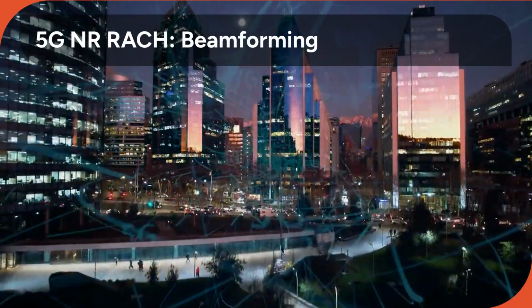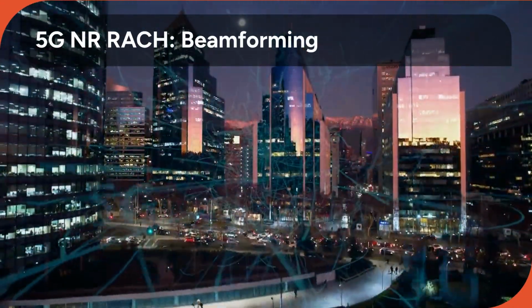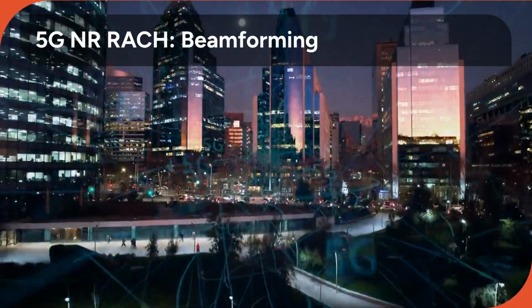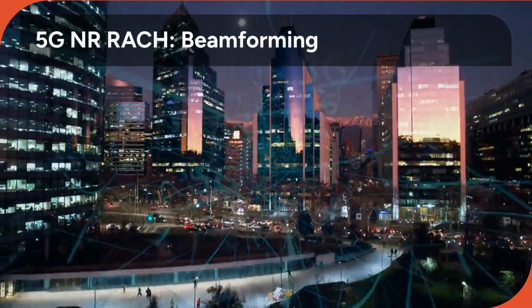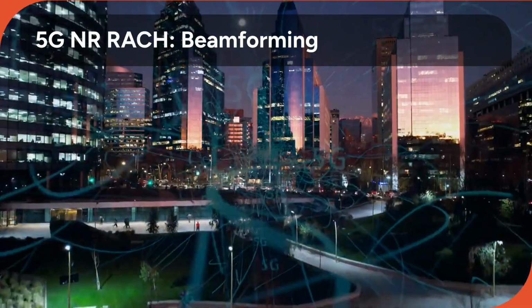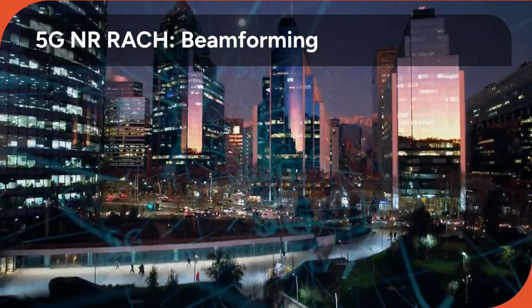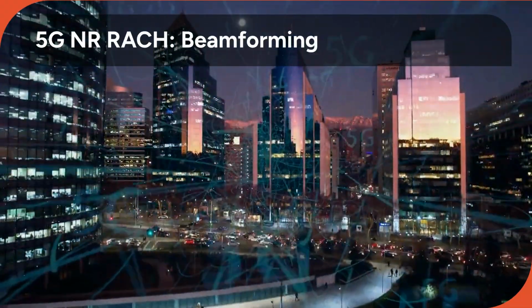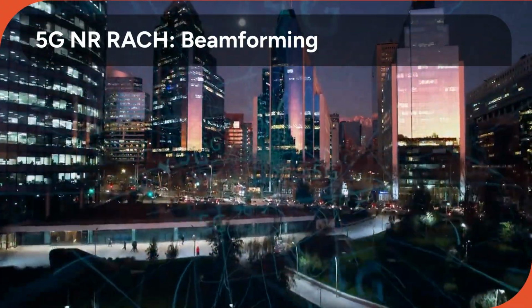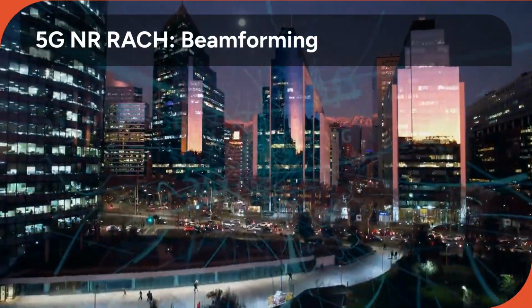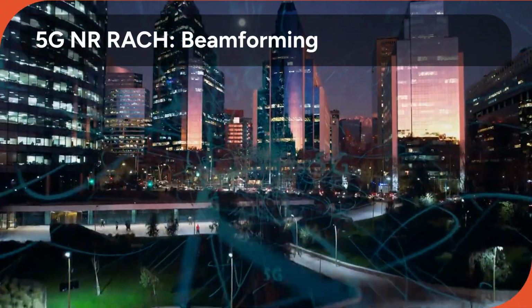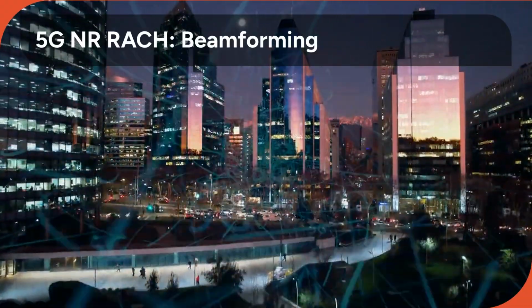Transitioning to 5G new radio, the fundamental process remains, but the context dramatically shifts due to beamforming, especially in millimeter wave spectrum. 5G RACH is inherently beam-centric. The question is no longer just, are you synchronized with the cell? But are you synchronized with the correct directional beam?